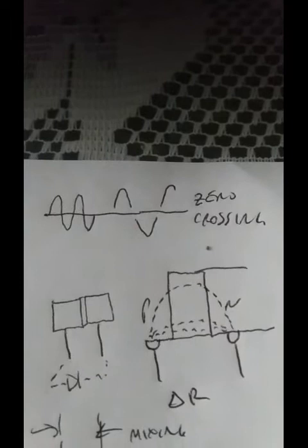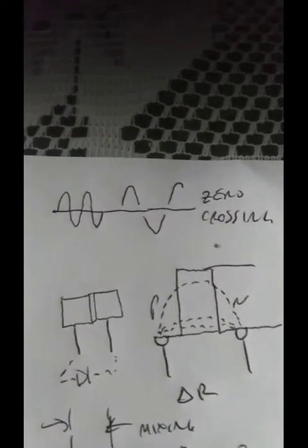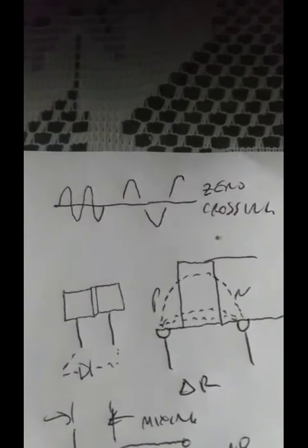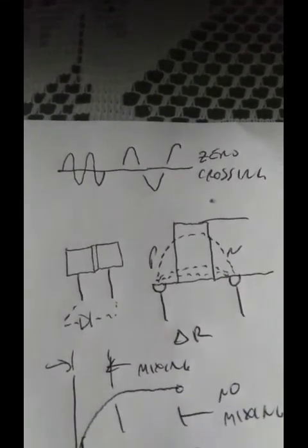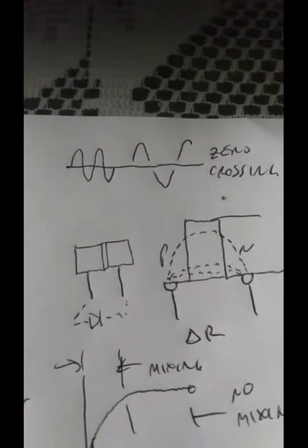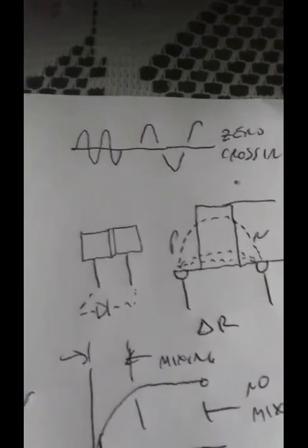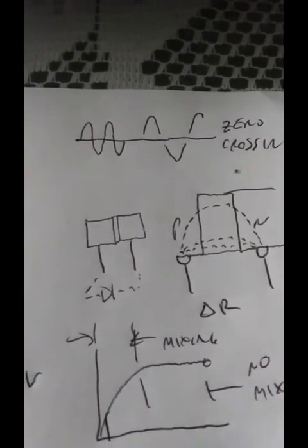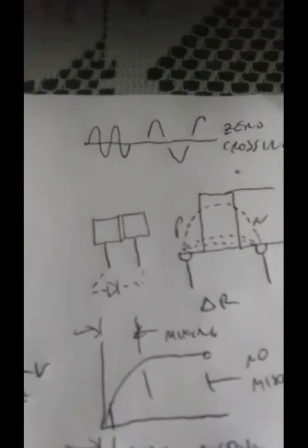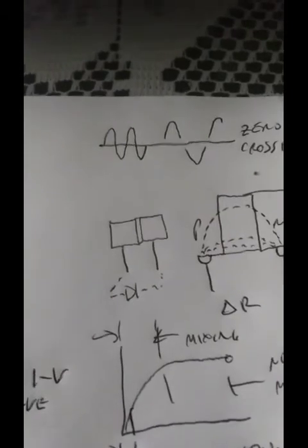That's why we can't use ordinary silicon rectifiers. They have a forward drop of generally 0.48 to well over a volt. And that contradicts this balanced modulator theory, which says that the carrier level must be relatively high and the modulating signal relatively low to be able to separate out the modulation signal. So what that implies is that we need diodes with a very low forward voltage drop.